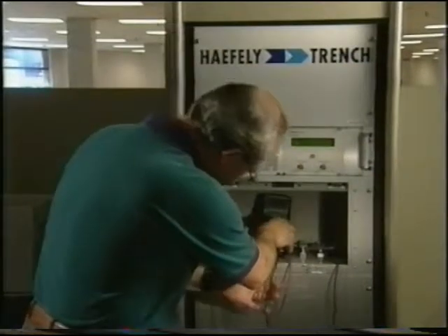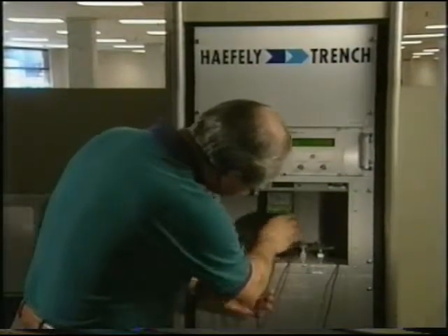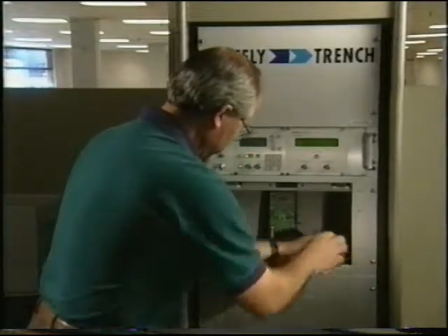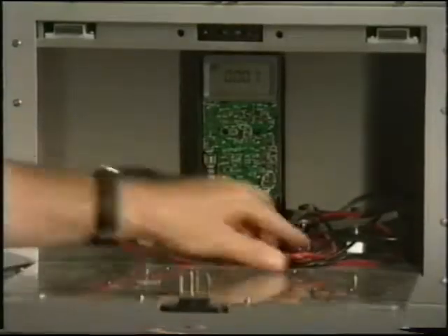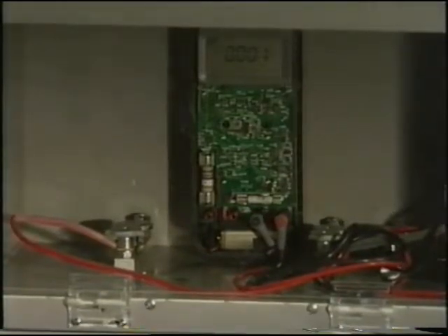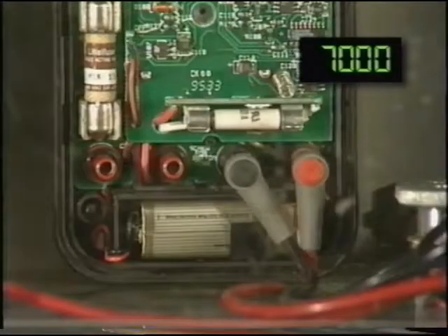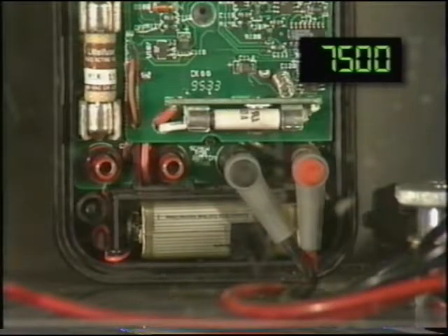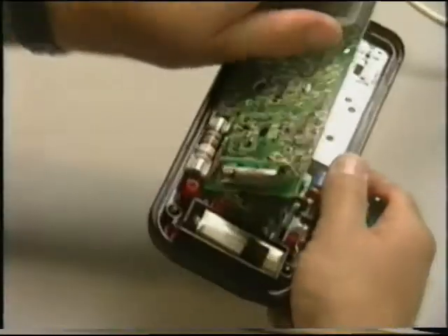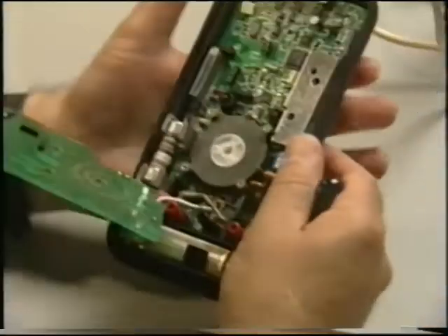Some manufacturers state that their products are designed to meet or conform to standards, but not every meter that makes that claim will pass the test. Here's what happened to a meter marked Cat 3 1000 volts when it was actually tested. Remember, the meter is supposed to withstand a minimum of 20 8-kilovolt transients. This meter failed twice before reaching 8 kilovolts, once at 7 kilovolts and again at just under 8 kilovolts, with a fault current of 2.8 kiloamps.